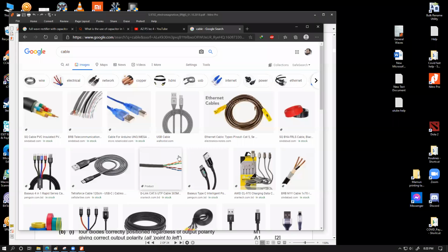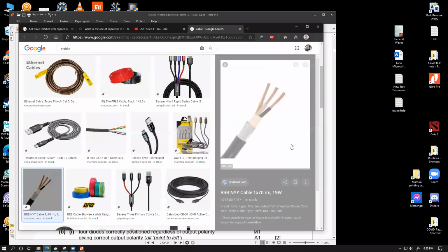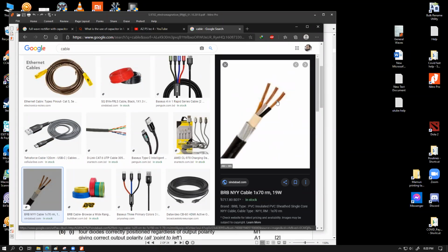Let's say this is one of the typical electrical cables, power line. So here you have three wires, live, neutral, and ground. But if you only consider live and neutral wire, what is the most likely distance between two of these metal leads through their insulation? That is the value of your D, for how close the two metal wires are supposed to be in reasonable normal circumstances. And what is the maximum current that you could possibly have? I calculated for a 1000 watt device on a 220 volt supply about 4.5 ampere. So these are the two values: about 2-3 millimeters for D, and about, let's say, 4.5 or 5 ampere for the current.